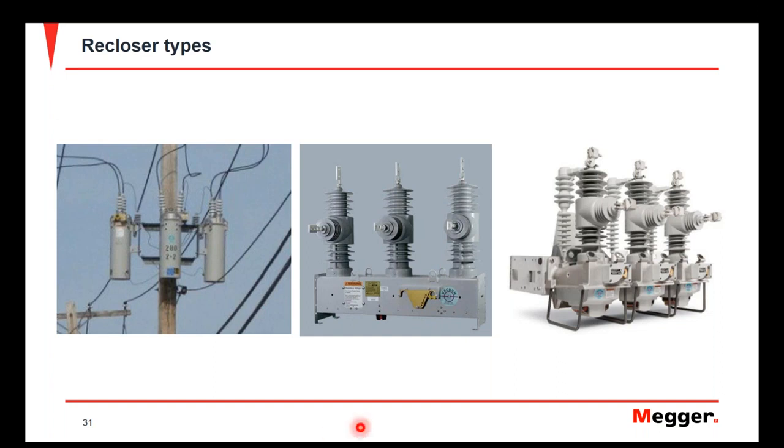Now, this one here is a 3-phase recloser, and the application typically for it is an application where you don't ever want the system to experience a single phase condition, such as a large motor or a transformer, that you just don't want it to see that single phase condition.